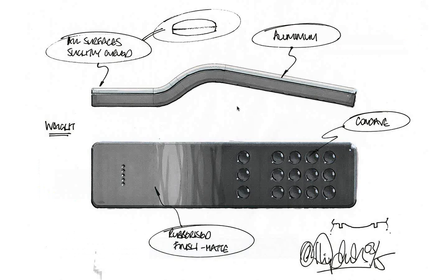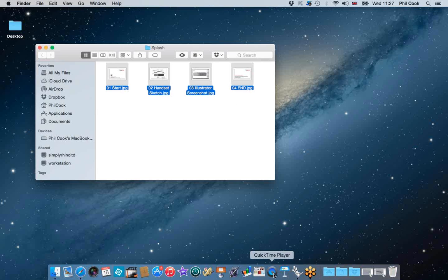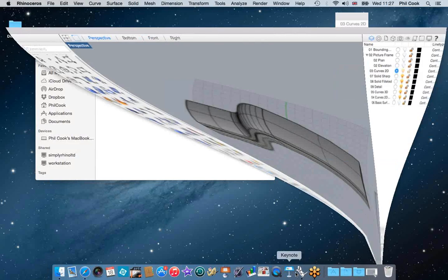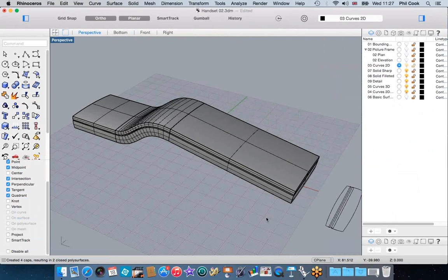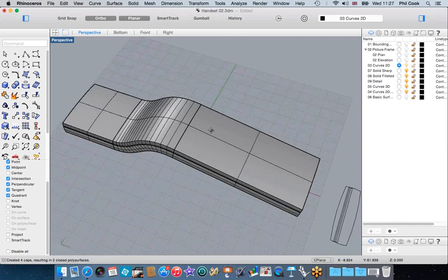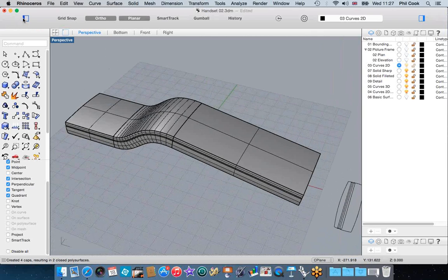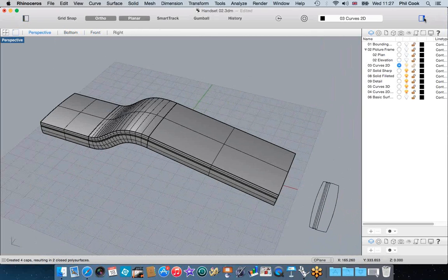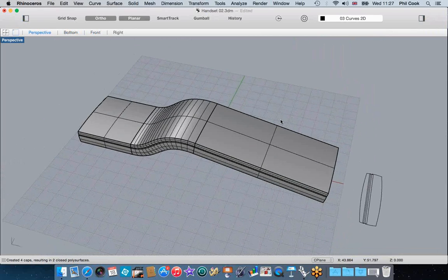Thanks for that. A few questions. Command line. I guess this is a question from someone who's using or seen Rhino for Windows, because they're asking where is the command line. Yes, well, actually, it's here, but there's no need to click inside this window and start typing. Wherever you are in Rhino, even if you don't have this section enabled, so even if you're working in a more full screen mode here, I can just start typing.